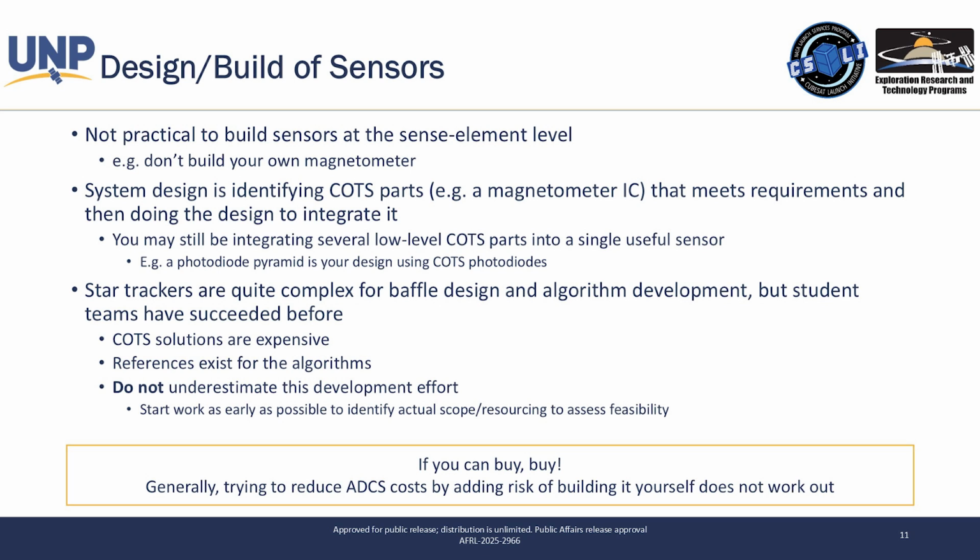The other thing too is if you have one plane of generation, that is not good enough to determine where the sun is. You need at least a couple points of your photodiodes to be able to say if the sun is behind me, I can still spot it and rotate around to point my panels at it. So that's the other big reason why we still just use photodiodes.